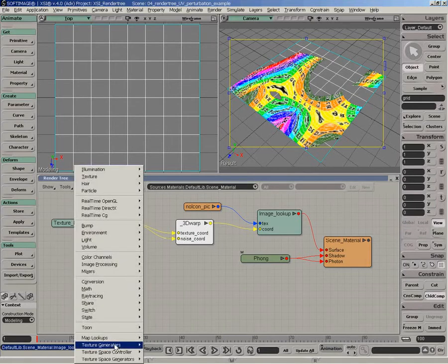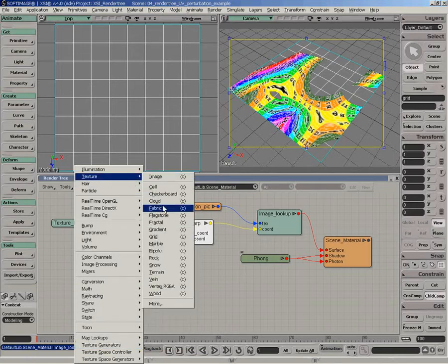What is quite interesting is that you could use other procedural shaders to actually perturb other textures. Let's say, for example, you have a texture generator. The difference between textures here is that these shaders are designed to look up their own UVs onto the object. So there's no way to insert any shader to modify the UVs. It's a closed shader that will look up its UVs, take these UVs and give them to a procedural node, which is cell, cloud, or fractal, and that shader will return the actual result from that UV position.